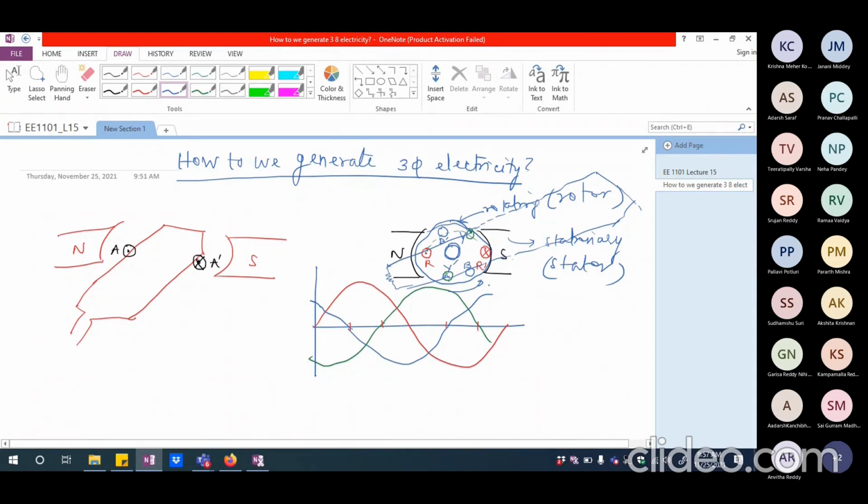They are also insulated from the core because it has to be inserted into the core, which is actually the outer periphery of the rotor. The rotor is going to actually have stampings again. You are going to have something like this as the rotor structure. So you can imagine this as the kind of teeth that is protruding in the rotor. Let me show it completely. It doesn't matter, it is taking some time. And I'm essentially having this like this. So I'm going to have the conductors inserted inside the slots like this.